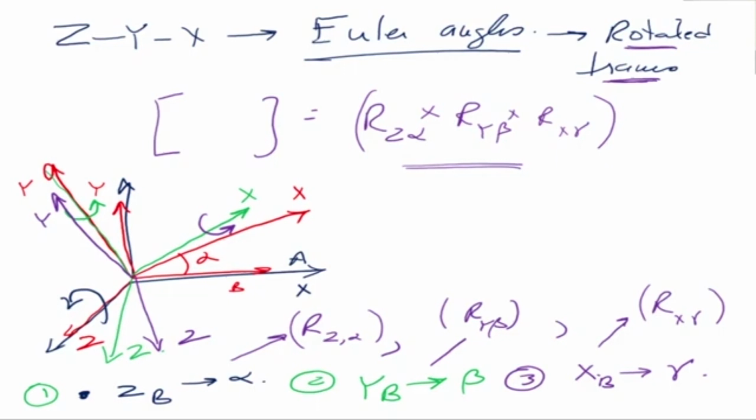Okay. Now this is something to remember, but in robotics we will normally go ahead with the fixed angle rotation only, because it gets a little confusing, as you can imagine. If you start rotating about the rotated axis, then your base itself is rotating with reference to that axis now. So the concept of putting a fixed base doesn't help. So it gets very confusing.